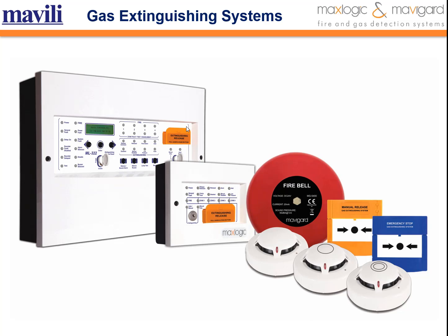Detection of fire alarms coming from detection zones by the system can be delayed for a standard time of 30 seconds. And all planned delay times, such as assignments to the outputs in the system, can be easily programmed. We have computer software to program our extinguishing panel, so you can easily adjust a scenario for your extinguishing system in the project. The panel has a flexible programming structure that can be equipped with local features in different and complex projects.